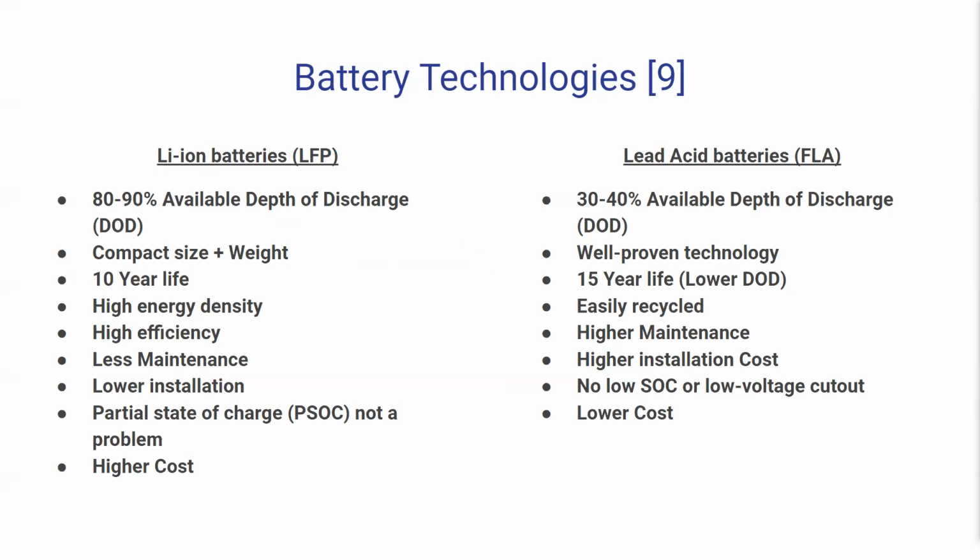The lead-acid batteries are kind of the contrast. They have a significantly lower depth of discharge at about 30 to 40%. They are a proven and low-cost technology that also has a long shelf life, but they do require higher maintenance and installation cost. But that still holds at a lower cost overall.